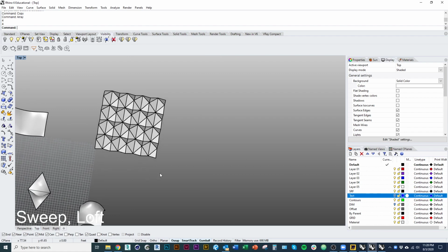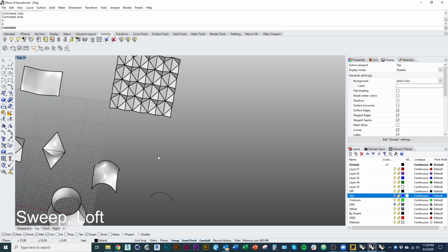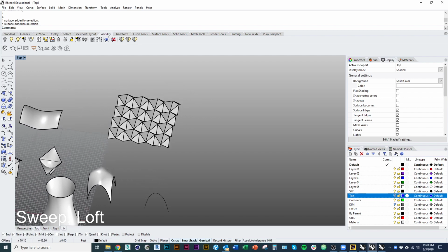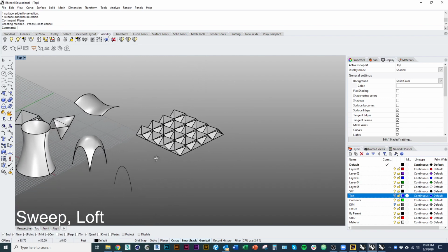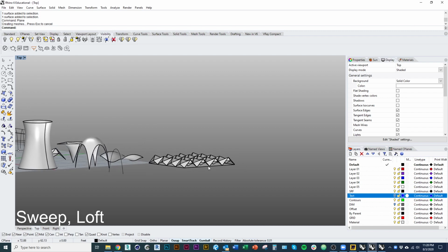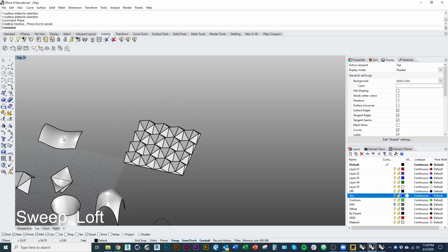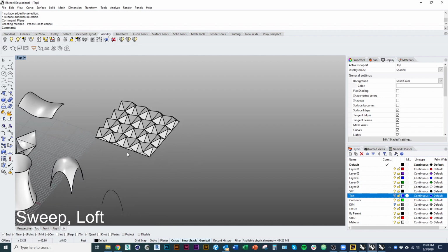And then, so let's say I took this pattern and I wanted to apply it to a 3-dimensional surface like this one or this one. Not 2-dimensional, but I took this geometry and wanted to apply it. What I want to do is make a base plane. So I'm going to use the plane command, and I'm going to go corner to corner. And so I could take this geometry relative to its base plane and apply it to a 3D surface using the command flow along surf.